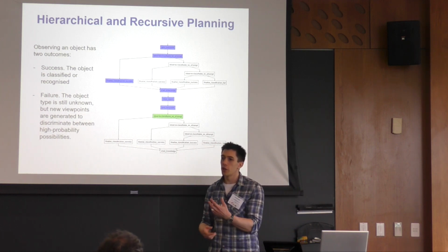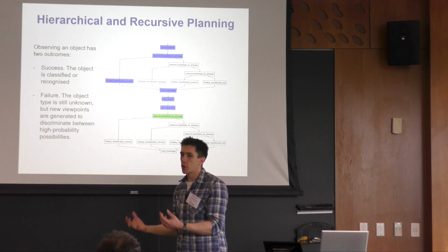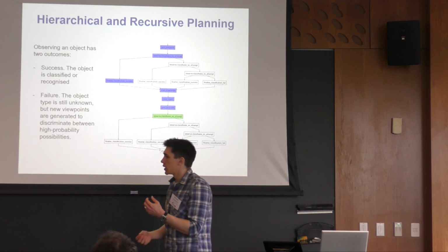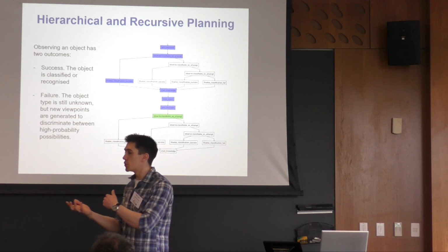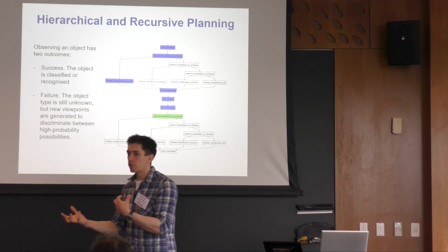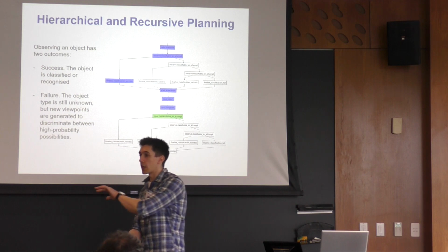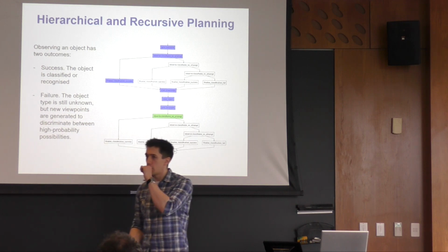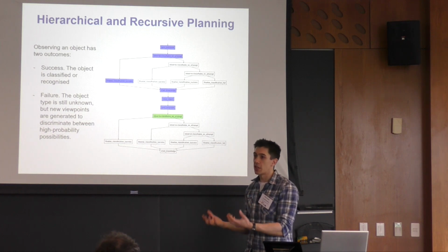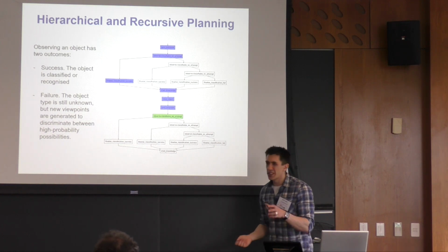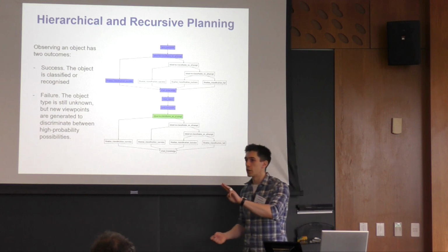So it moves into a room, first of all, without knowing where any of the objects are. Then once it's identified where the objects are, it generates a set of view cones around each object from which it will start to build a 3D point cloud. After each view cone has been visited, it makes an attempt to identify the object. This identify action has actually 3 outcomes.